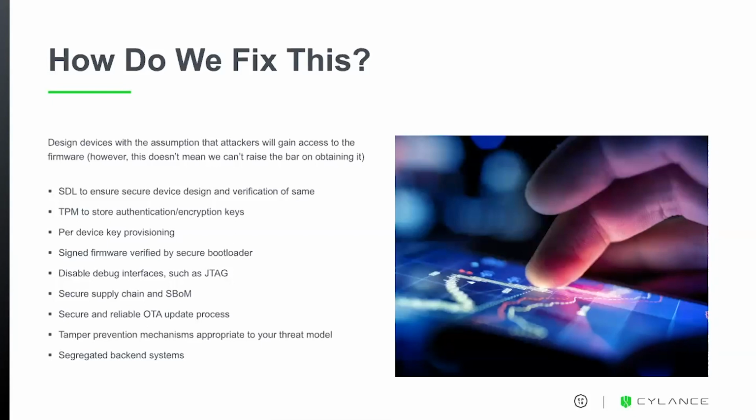If we need to store sensitive authentication or encryption material on a device, we want to do it with a trusted platform module. This is a high security chip, almost a high security microcontroller, that makes it very difficult to gain access to these sort of keys. But the takeaway there is we want to store them in a secure fashion, so we can't just extract them from a device and then reutilize them to compromise the supporting systems. Per device key provisioning, so that if we compromise one given system, we can't utilize that to compromise all the other devices as well.